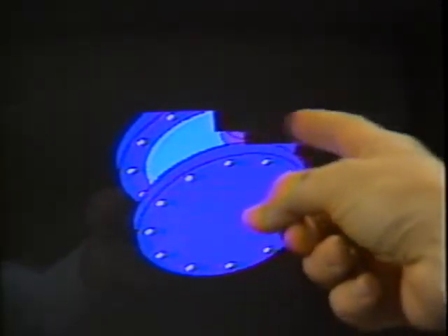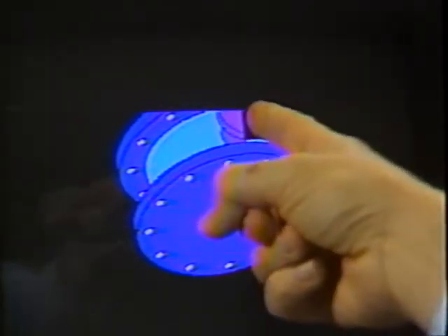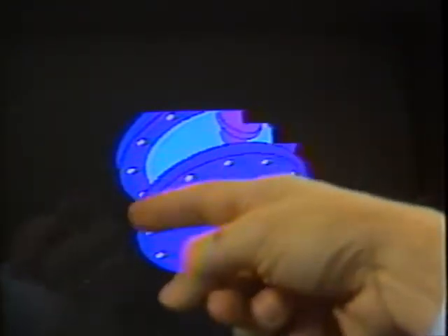Notice the stem guide primitive is beginning to appear here, and again, it's nothing more than two cylinders union together and then joined to the middle portion. We now have the sub-assembly created from which we can extract the material to form the internal geometry of the valve and come up with our finished model.